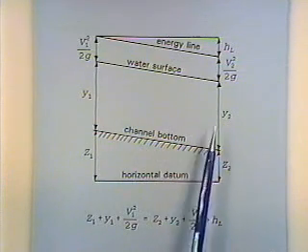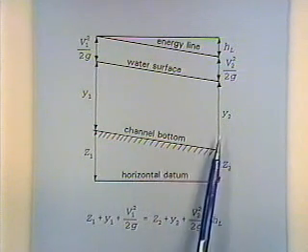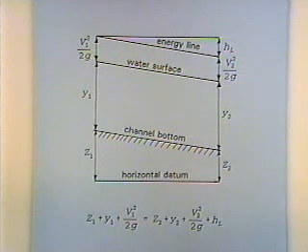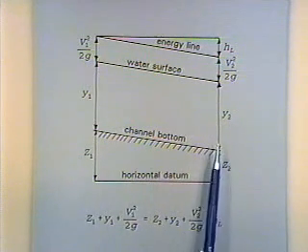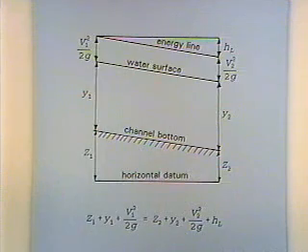Now gradually varied flow means the depth changes along the length of the channel. And so what we'll be doing is having a known depth someplace, computing the depth all along the channel. There's two ways of doing that. Conceptually, we're working with the energy equation using Manning's equation to estimate head losses either way, but the computational details vary between the direct step method and the standard step method.